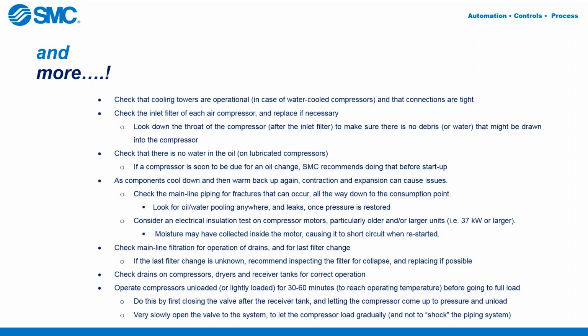Check that there's no water in the oil on lubricated compressors. If the compressor is due for an oil change or soon to be, I would change it. If it's sat idle for a while, best to change the oil before starting up. You might note that as components cool down and then warm back up again, contraction and expansion could cause some issues. So a walk of the mainline piping, looking for oil or water or discoloration, and once pressure is restored, a check for leaks might be helpful.